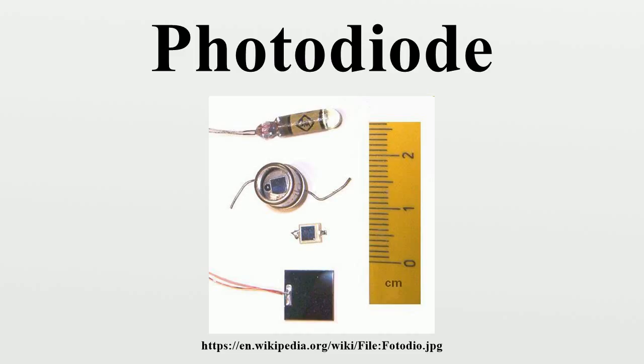Noise equivalent power. The minimum input optical power to generate photocurrent, equal to the RMS noise current in a 1 Hz bandwidth. NEP is essentially the minimum detectable power. The related characteristic detectivity is the inverse of NEP, and the specific detectivity is the detectivity multiplied by the square root of the area of the photodetector for a 1 Hz bandwidth. The specific detectivity allows different systems to be compared independent of sensor area and system bandwidth.